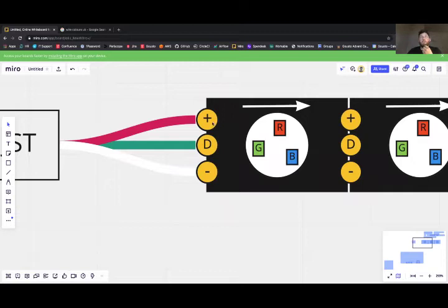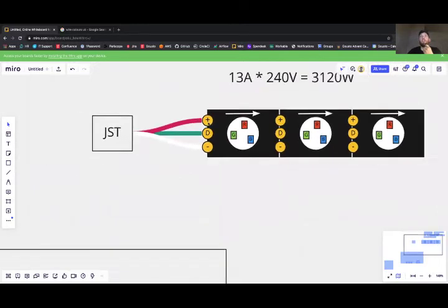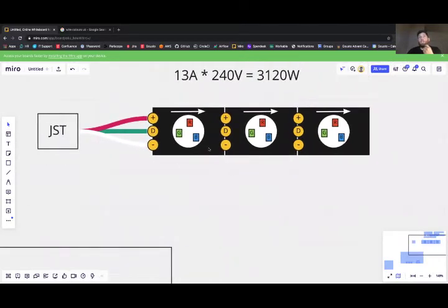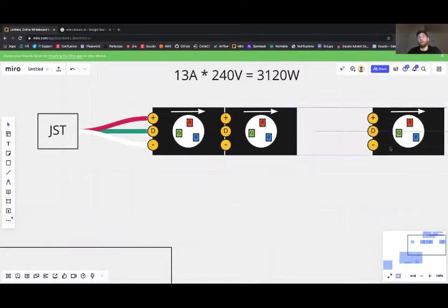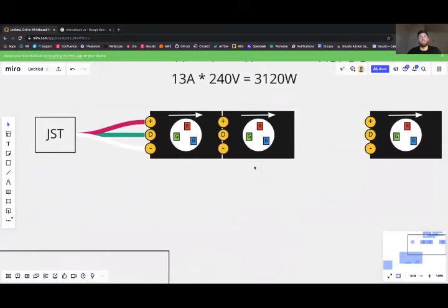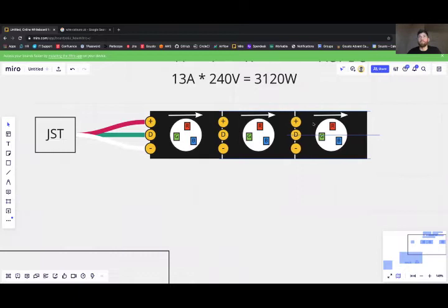These are literal copper pads, which you will be able to see on the circuit board and are required to make that connection. If you wanted to take a 1 meter strip and cut it into a ½ meter strip, for instance, you could simply cut along those copper pads and then add another JST connector in. How do you add stuff in? Well, you need to solder, and we're going to get onto that in a second.